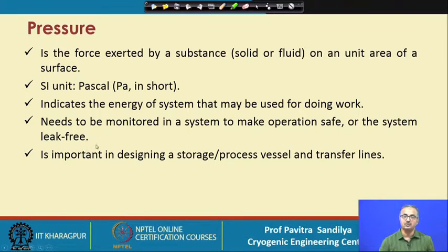Then we need to monitor the pressure in a system so that the system can be operated safely and without any leak whenever we are talking of any kind of storage or transfer. So whenever we are designing any kind of storage or process vessels and transfer lines, we have to take care of the pressure inside, because in the storage vessel, for example, if the pressure suddenly goes up beyond the design pressure, it may lead to explosion.